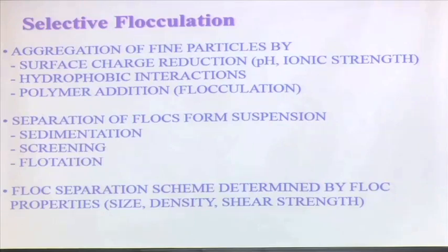Okay. Then separation of flocs from suspension: we have a floc, but how do I separate it? You have made a size enlargement, but now I can pass it through a screen, I can use a sedimentation process and allow it to settle because of its mass, or maybe I can use flotation because the size enlargement is there, I can use flotation again to separate them out.